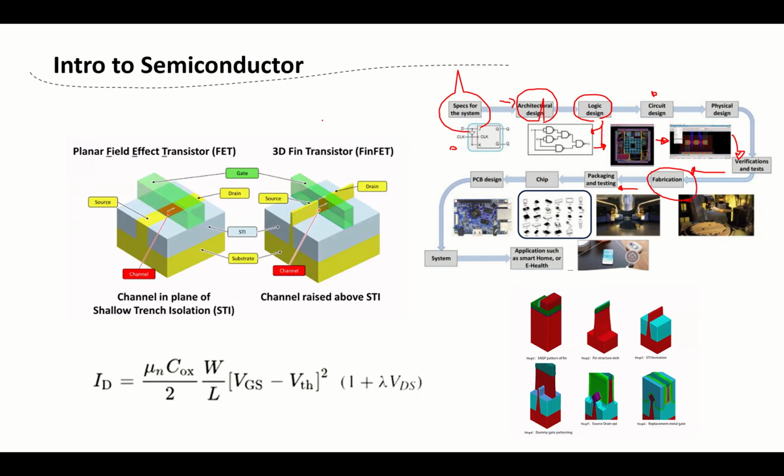So for packaging, there will be a PCB. Then there is something called an interposer. In the interposer, we have a C4 bump and RDL. Then we have TSV, through silicon vias. Then RDL again. Then bump. And this whole part is the interposer. After that, we'll have chips like the CPU, then HBM. They package it into one on one interposer, so we can have better throughput and smaller latency.